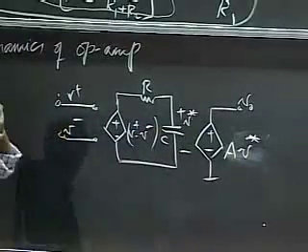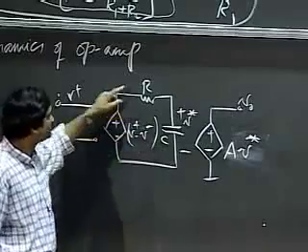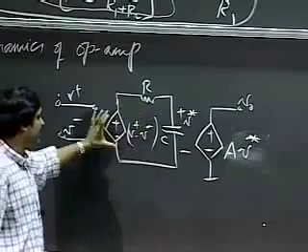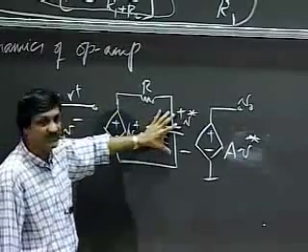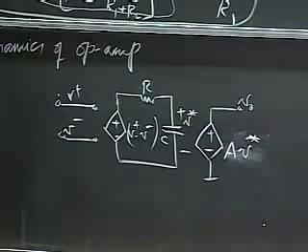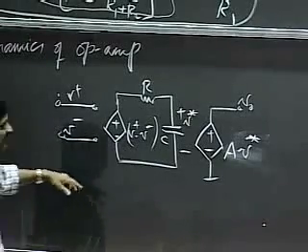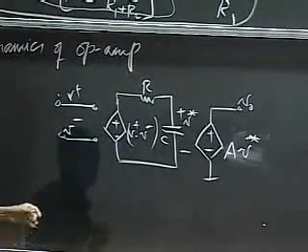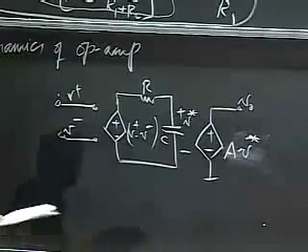Notice that if it turned out that the resistance here, for example, was 0, then V plus minus V minus would appear across V star, and this would be A times V plus minus V minus, what you've seen before. It's always good to take a look at circuits and look at what happens when some component goes to an extreme value. This would give you your basic op-amp circuit.